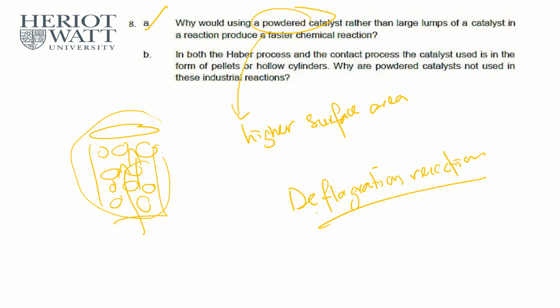When it burns, these small particles will actually mix with the catalyst particles as well. And then there is a heat transfer, or the heat wave, from the small particles of the reactants towards the catalyst powder. That transfer creates a huge hot air wave, and that will continue the combustion of the particles, and that causes an explosion at the end. So that's the reason why they try to avoid using powdered reactants or powdered catalysts, because under certain temperature and pressure, that will favor deflagration and cause an explosion. All right, so that's the answer.